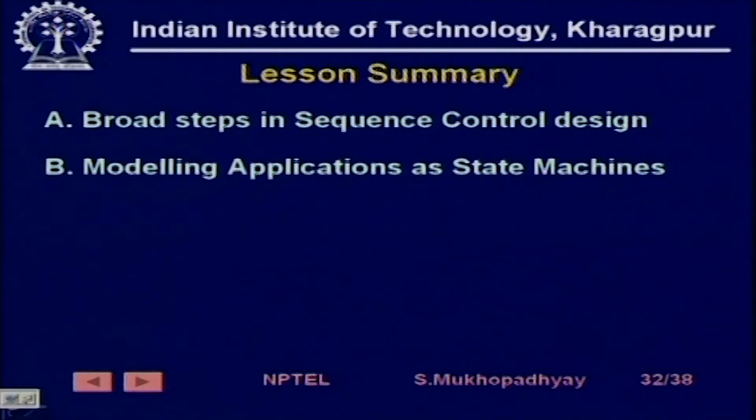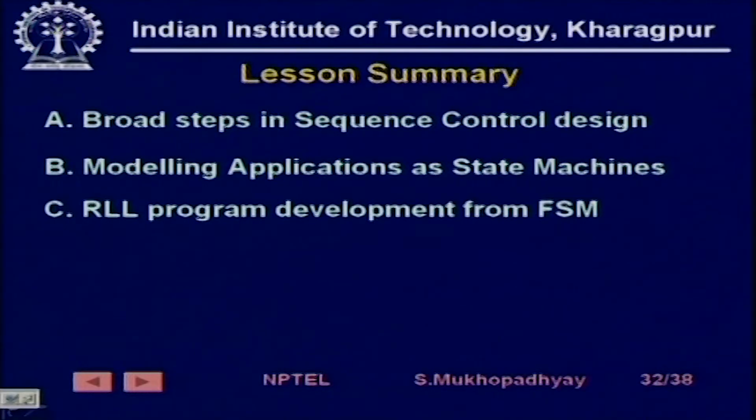We took a very simple industrial application like a stamping process and built its state machine, and then we have shown how, given the state machine, very mechanically you can arrive at how you can actually structure your program and then write the transition logic and the state logic and the output logic, and we have seen that this is very much expected to lead to error free programs.